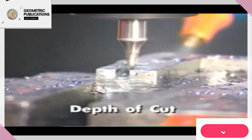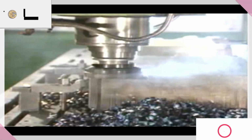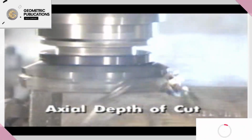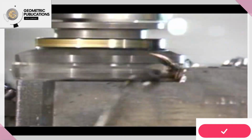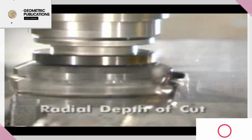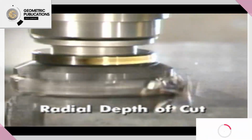There are two types of depth of cut, axial and radial. In face milling, the axial depth of cut is the distance the tool is set below the unmachined surface. Ordinarily, an axial depth of cut is selected to minimize the number of passes required to remove a given amount of material. The radial depth of cut is the width or distance of work surface engaged by the tool.